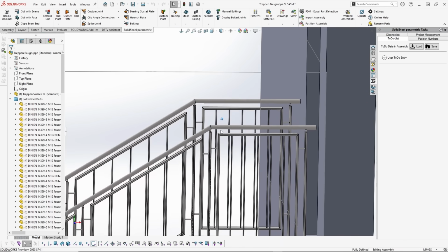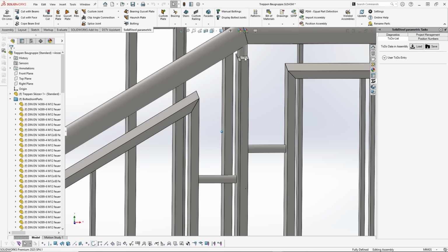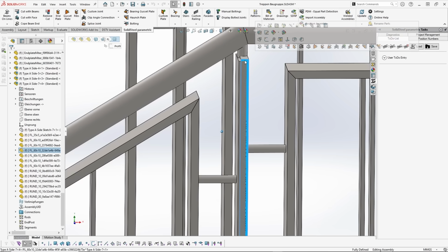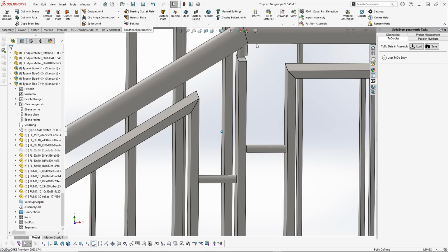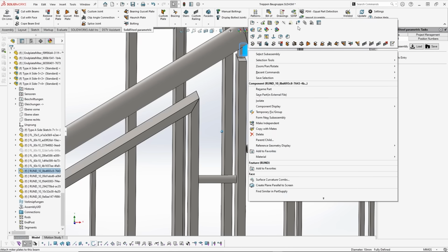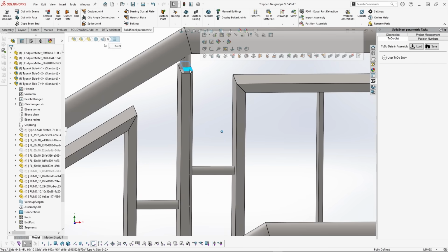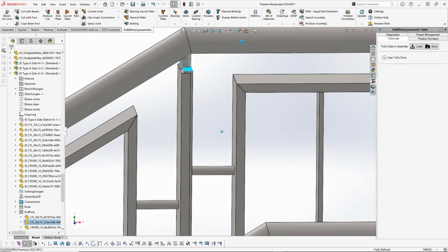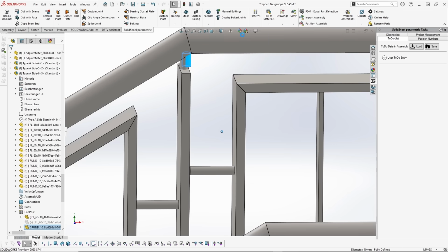You may remember that we placed the railing posts on top of each other earlier. To ensure the bill of materials is correct later on, we now select the parts of the redundant post and suppress them. The small round bar as well.